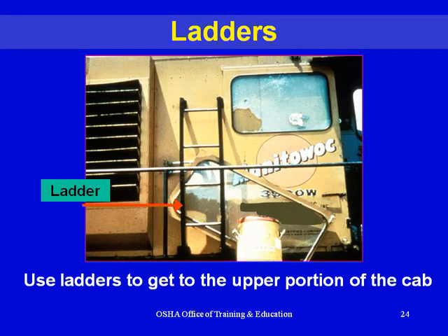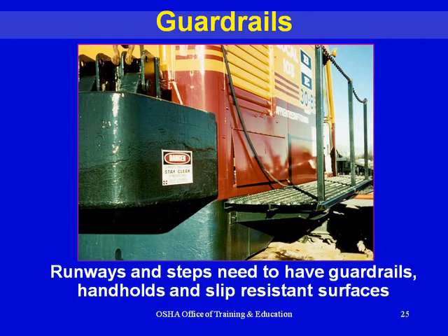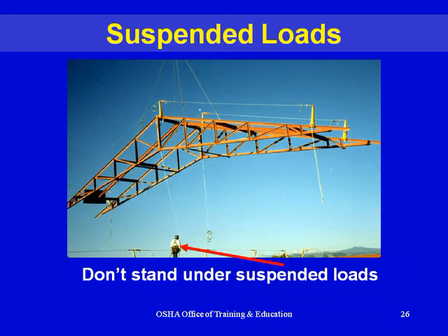Ladders. Use ladders to get to the upper portion of the cab. Guardrails. Runways and steps need to have guardrails, handholds, and slip-resistant surfaces. Suspended loads.